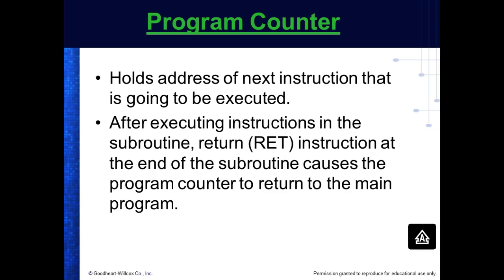So what you can do on the PLC is go through the same section until you get all the bugs out of the subroutine instead of trying to find it inside a section of the PLC program. And this is why we call this structured programming. We break these large programs into individual little sub-modules, and then I can play around with a sub-module without affecting anything else.